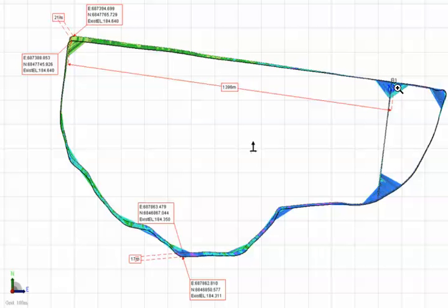So, and then we shifted both, we shifted the multiplane coordinate system so that the master benchmarks lined up. The GPS Ag system saved the coordinates in eastings and northings. You can see with this large number here, and using the GPS datum ellipsoid, and then we shifted the multiplane so that they matched up at the master benchmark, and then we wanted to see the difference at the extremities.